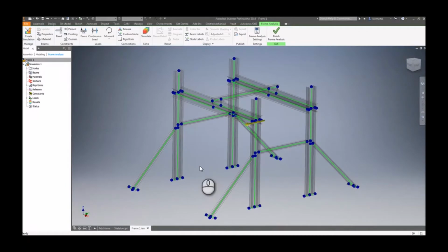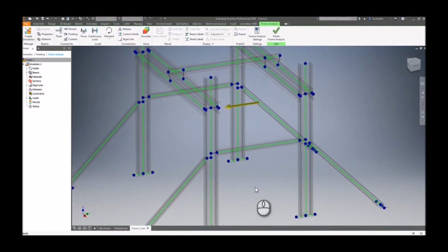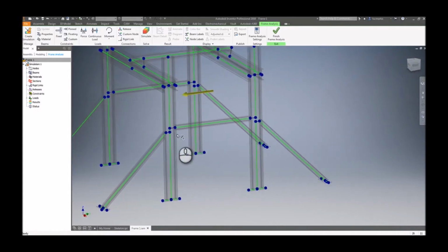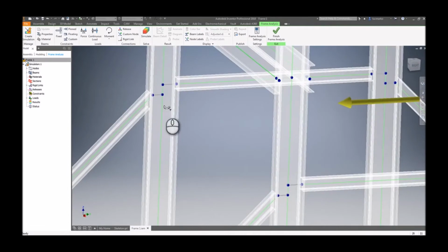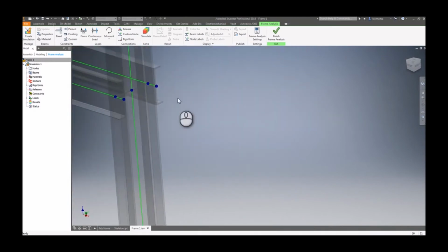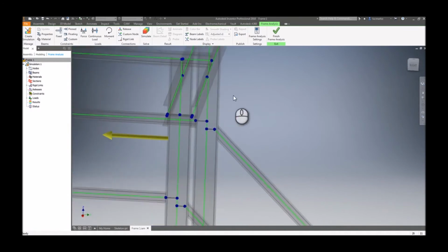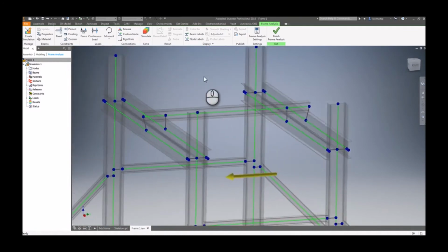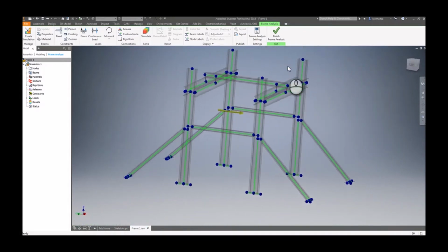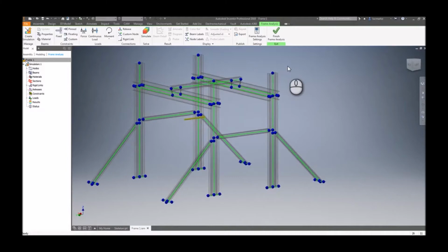As you can see, Inventor is creating the same skeleton that we did to create the structure, but in this case the elements have a connection between them. Those elements are connected with something called rigid links, and it is placed automatically. Inventor recognizes the elements, but it only recognizes frame generator elements. If you sketched the beam and did an extrusion, it is not going to work.